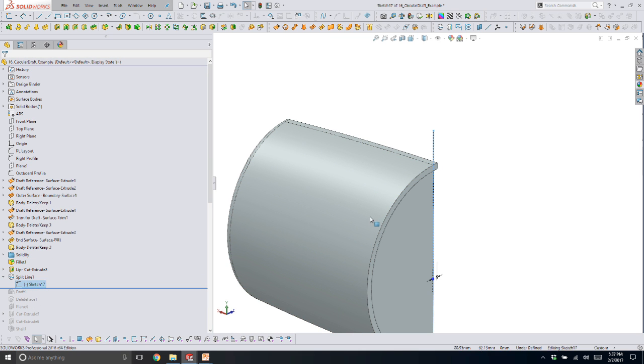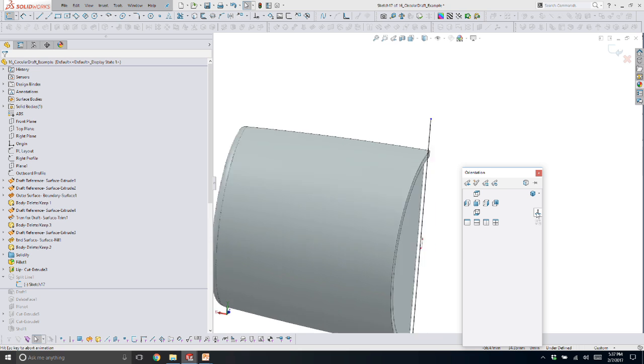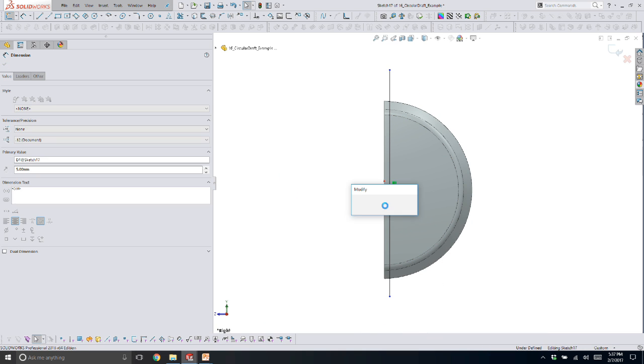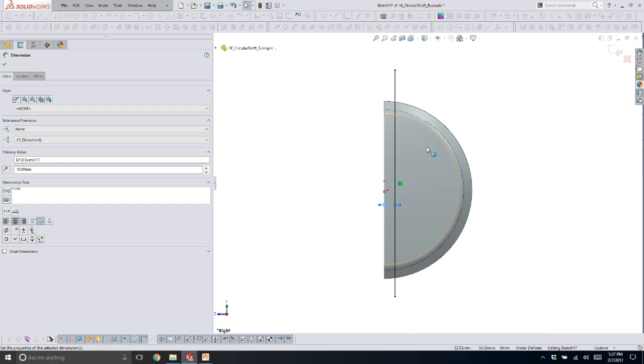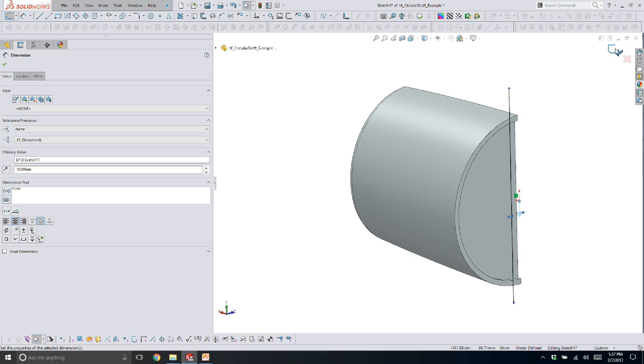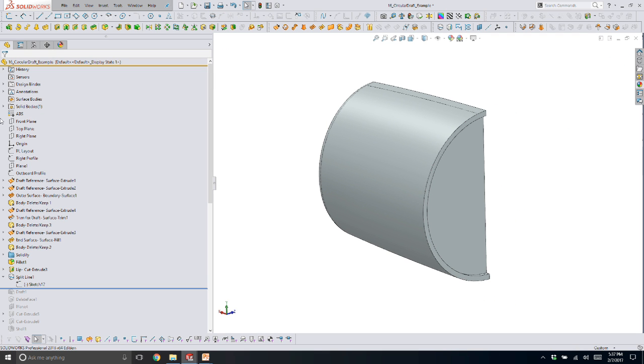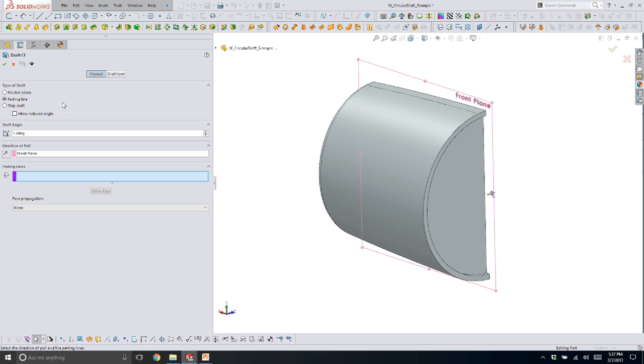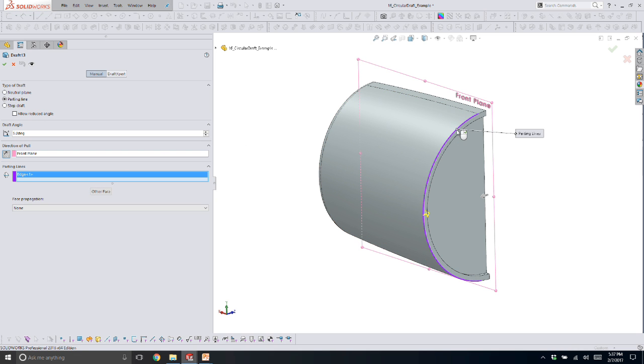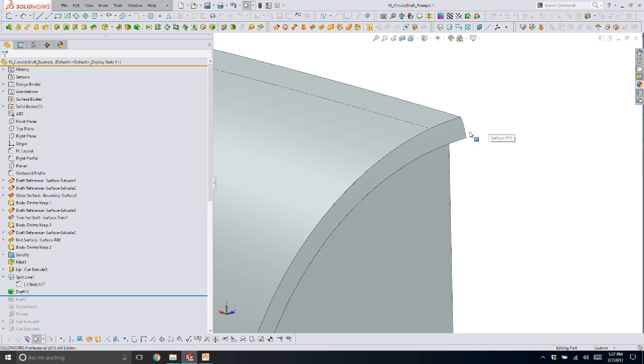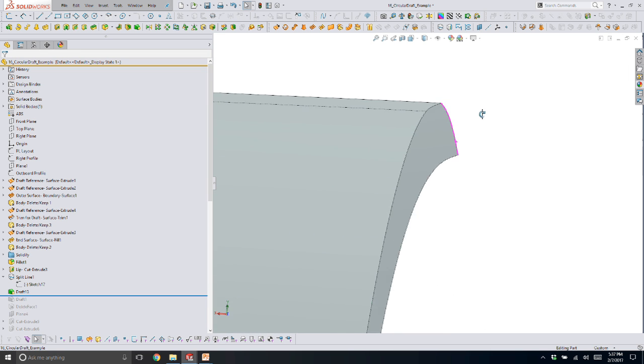The way I set this feature up is I just start with a sketch, and then I usually go more than I think it should. So here, let's go 10 millimeters, and we're going to add our parting line draft at the 5 degrees. It's coming this way out of the tool. We're drafting from our cosmetic edge, keeping it straight. And now SolidWorks is able to figure out that extension.